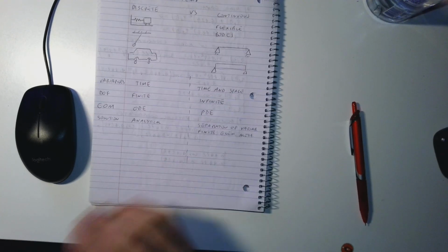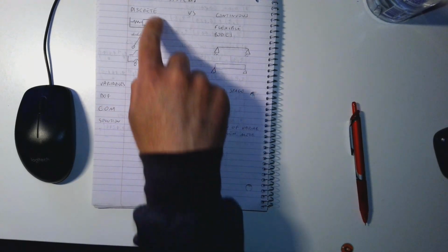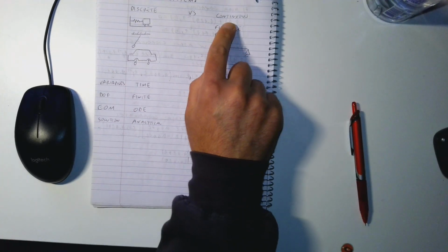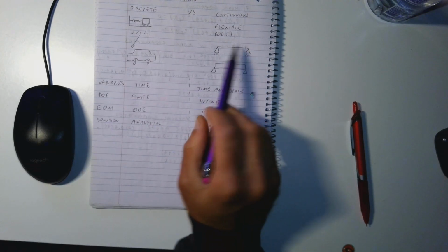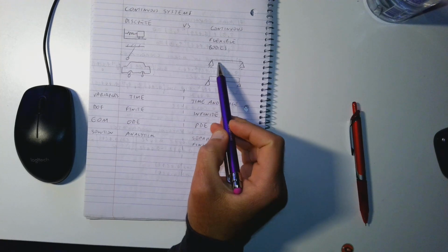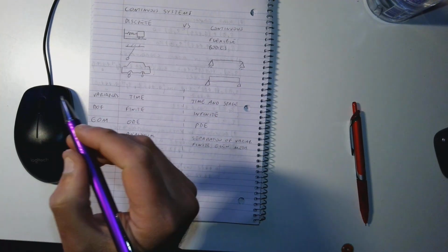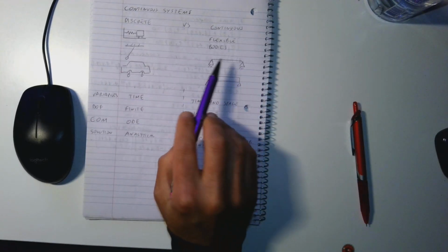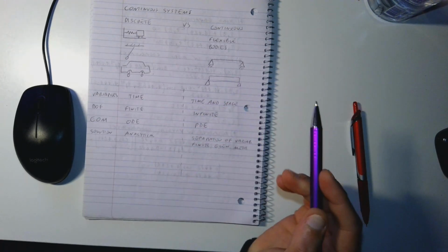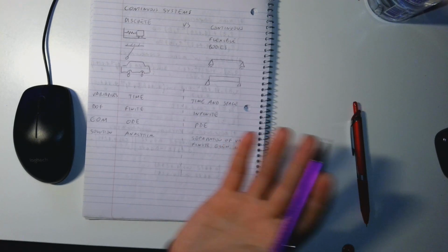For now we will focus only on 1D systems, which means we have one time variable and one space variable. Another difference is that the number of degrees of freedom is finite when we look at discrete systems, and infinite when we look at continuous systems. This is because when we look at the deformation of this string, every point can be considered a degree of freedom. If we look at the entire length, we have infinite points between the beginning and the end of the string. So it means that we have an infinite number of degrees of freedom, and this is why we have to approach the problem with different tools.